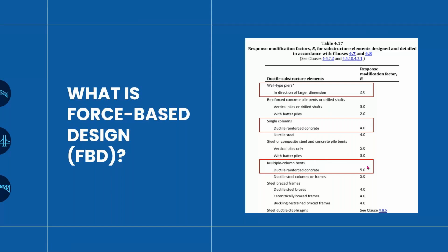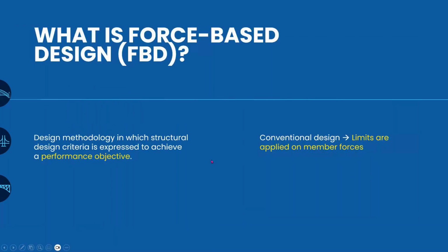So from this we understand that most of the force based design principle revolves around this response modification factor, and most of this concept is based on past experiences.